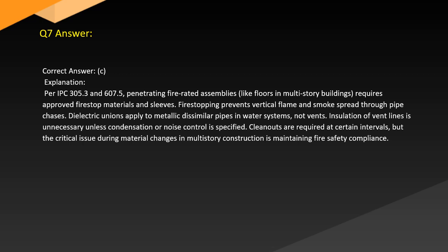Answer. Correct answer: C. Explanation. Per IPC 305.3 and 607.5, penetrating fire-rated assemblies like floors in multi-story buildings requires approved fire stop materials and sleeves. Fire stopping prevents vertical flame and smoke spread through pipe chases.